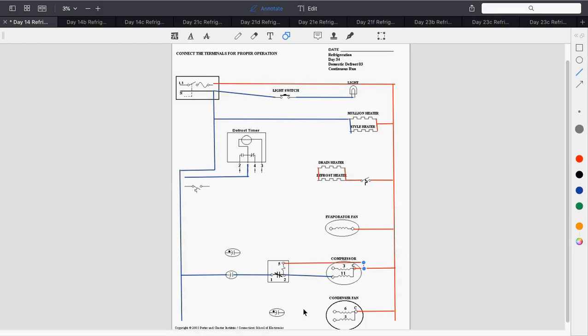Okay, so again, whenever we have a pin 1, 2, and 5, pin 2 connects to the start winding, pin 1 gets the start capacitor, pin 5 goes to common. Where does that run winding connect to? To the other capacitor that's above the other one. Nope, nothing. Well, you could put it there, but it's only on the voltage feed side of that. We never put a capacitor before the run winding.